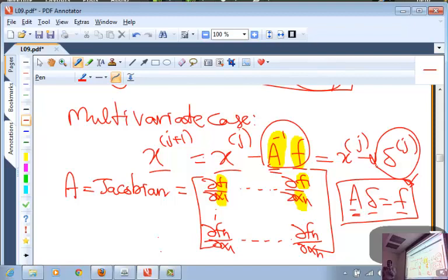But you may not know initially. To begin with, the initial guess may not be close enough. So you apply this. These are all practical tricks that COMSOL and Fluent will use to enhance the range, so that you can throw any initial guess and it will still hopefully converge. Okay. So the Newton method and the Jacobian is going to play an important role in the next couple of lectures, where we develop the continuation method, the arc length continuation, the Euler-Newton continuation, and tracking of the singular points. And that will give us a very strong foundation for analyzing any nonlinear algebraic system.